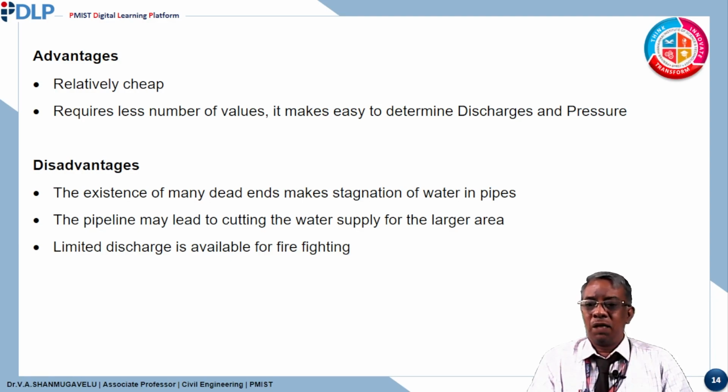There are disadvantages. The existence of many dead ends makes water stagnate in pipes. The wastage of water will be increased. A break in the pipeline may lead to cutting the water supply for a large area. Limited discharge is available for firefighting.